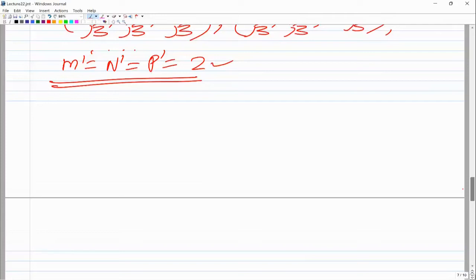The only change is in the sizes of the matrices and the shape functions. The development of the element level governing equation, assembly, imposition of boundary conditions, and solution remains the same. So I will tell you how to write the shape functions for a 2D 8-noded isoparametric element, and then I'll move on to the plate bending elements.